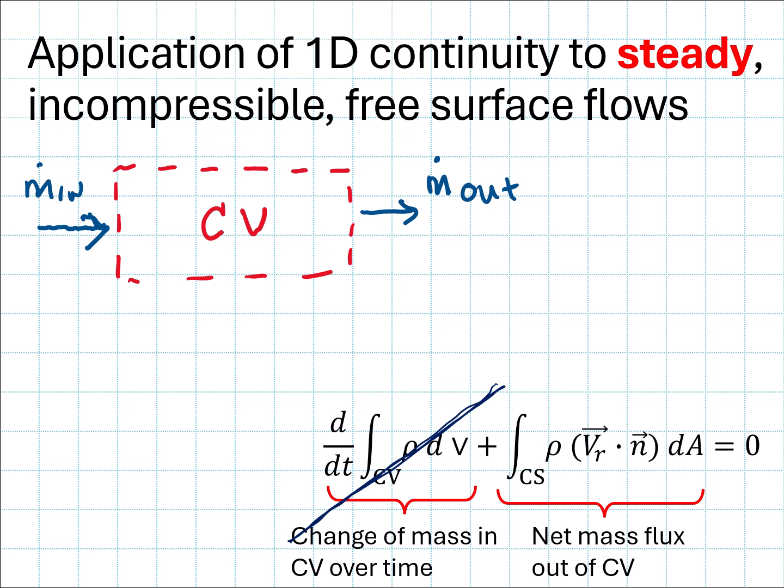So if I just think about this dimensionally, right? If I've got a density multiplied by a velocity multiplied by an area, and I replace each of these terms with their dimensions, my density is going to be a mass per cubic length, my velocity is a length per unit time, and my area is a length to the power of 2. So overall, I'm going to wind up with a dimensionality of a mass per unit time, which is, of course, the dimensionality of my mass flux rate, m dot.